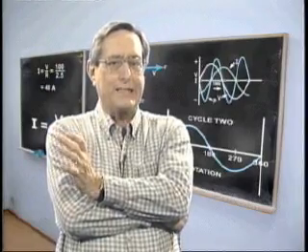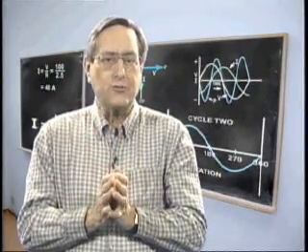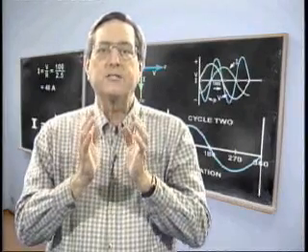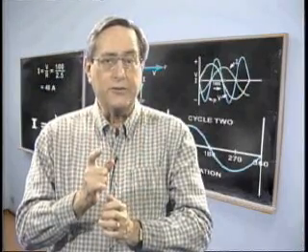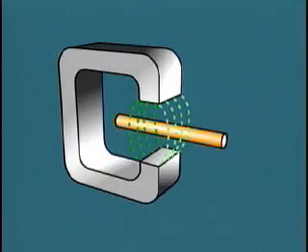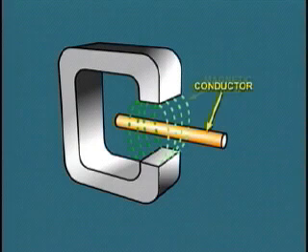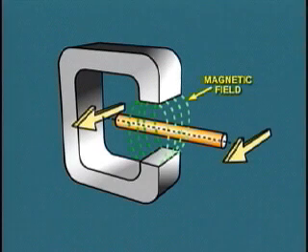Clearly, this subject of magnetism is opening the door to many concepts. One extremely important set of natural laws, discovered by a Mr. Faraday many years ago, provides the basis for all electromagnetic induction machines, including generators and motors. This diagram shows the three conditions which must exist in order to produce voltage by magnetism. First, there must be a conductor in which the voltage will be produced. Secondly, there must be a magnetic field. And thirdly, there must be relative motion between the field and the conductor.